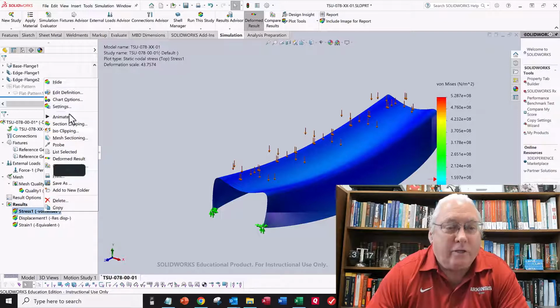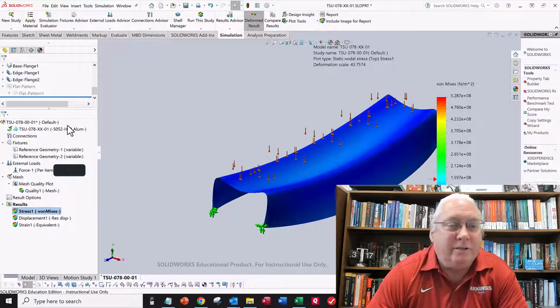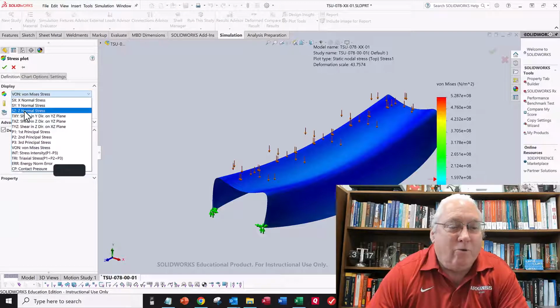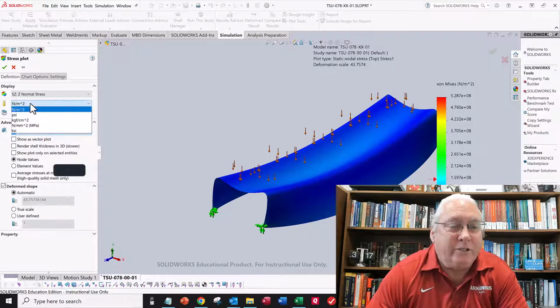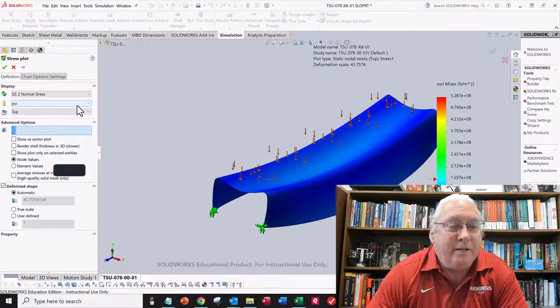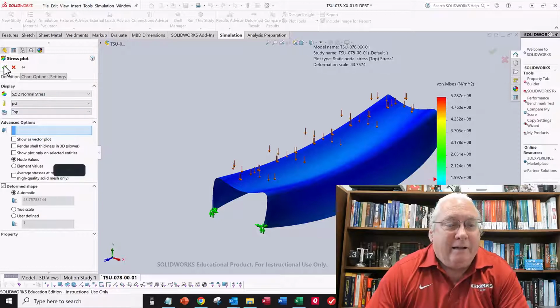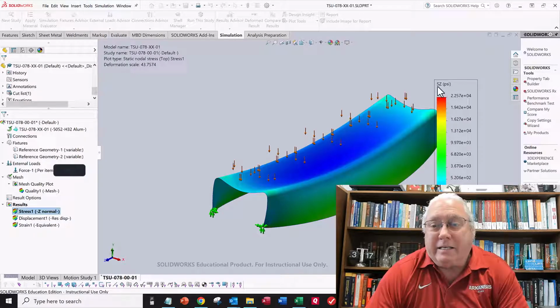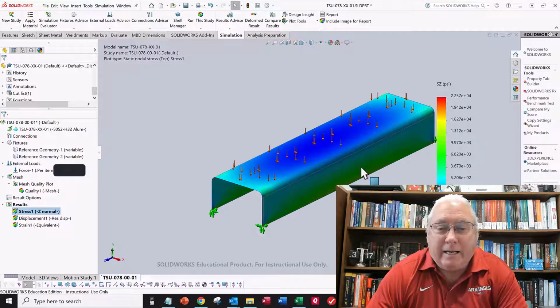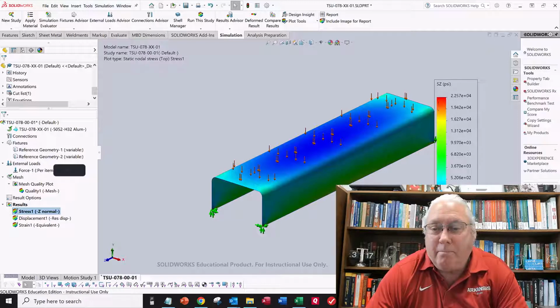So I'm going to right click on stress 1 and say edit definition. I'm going to change the definition of those results. Instead of asking for the von Mises stress, I'm going to tell it to give me Z normal stress. That's what we calculated in the last video. I'm going to change these units to PSI because all my numbers are in pounds and inches, in PSI. And that's it. I'm going to say OK. And it's giving me this deformed shape. I don't like that deformed shape. I'm going to turn it off so it goes back like that. So now I can see my maximum and minimum stress.